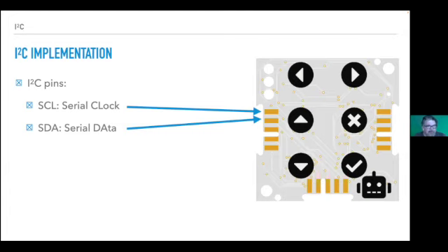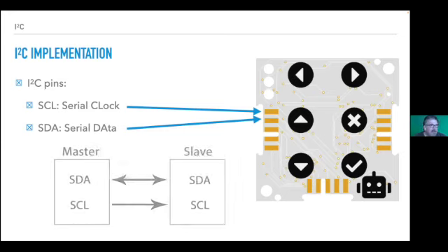So the way we have it here, so you recognize hopefully this core here, those two pins on the top surface, that's the two pins we're using for this I2C. So the first one is SCL, and then the second one below is serial data. And maybe just so there's no confusion, the clock is only the master that can send data out of that. The slave will never send anything.